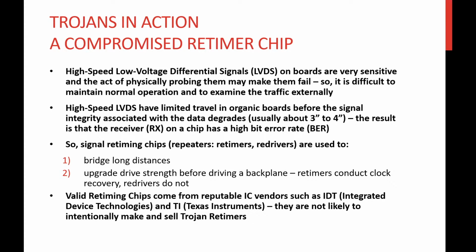PLL or DLL, delay locked loop. The clock recovery signal is embedded within the data so that the transfer is fully asynchronous. The data is created with the source clock, and the receiving device extracts the data with its own clock.